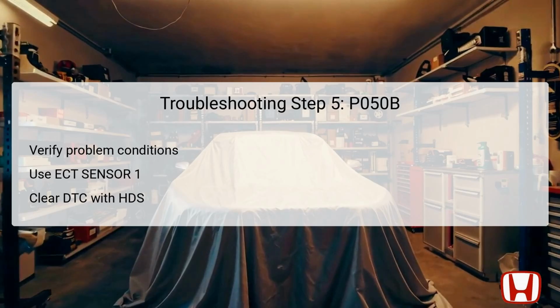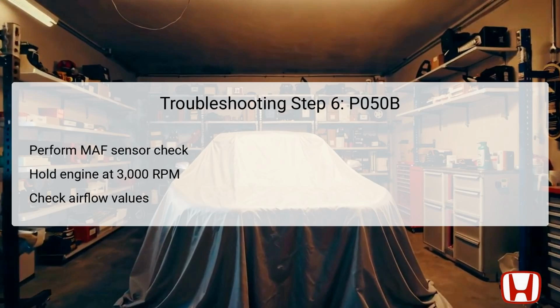P050B in the menu. If the HDS indicates failed, the problem likely still exists. However, if it shows passed, the system may be functioning correctly at this moment, requiring further inspection only if codes reappear. Step 6 involves conducting a performance check on the mass airflow sensor, which is essential for monitoring the volume of air entering the engine.